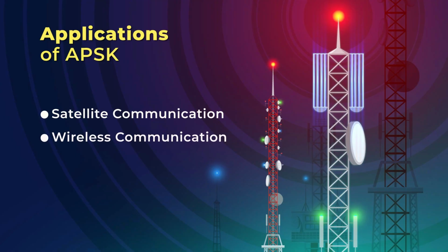The next application is wireless communication. APSK can be used in wireless communication systems that require high data rate and efficient bandwidth use. It is particularly useful in scenarios where power efficiency is also a concern, as APSK can be adapted to balance spectral and power efficiency.